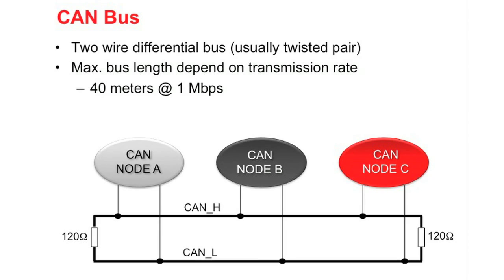Most microcontrollers in the Hercules platform integrate either 2 or 3 separate DCAN communication modules. One of the most common uses for the DCAN module is as a communications channel between electronic control units. Since CAN messages usually are transmitted beyond a single circuit board from control unit to control unit, the physical bus is most commonly comprised of a 2-wire twisted pair where differential signals are transmitted.